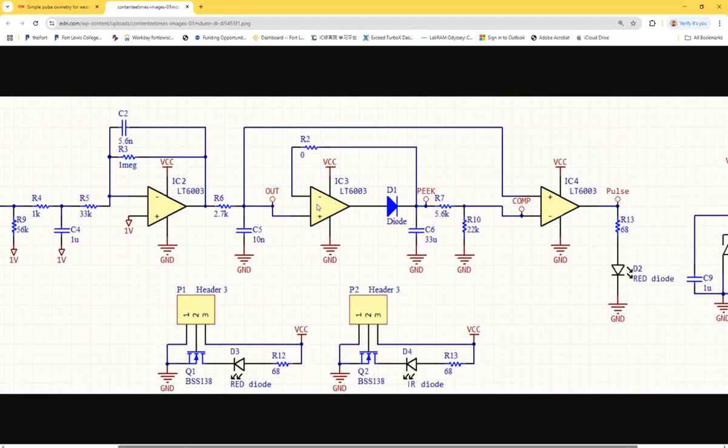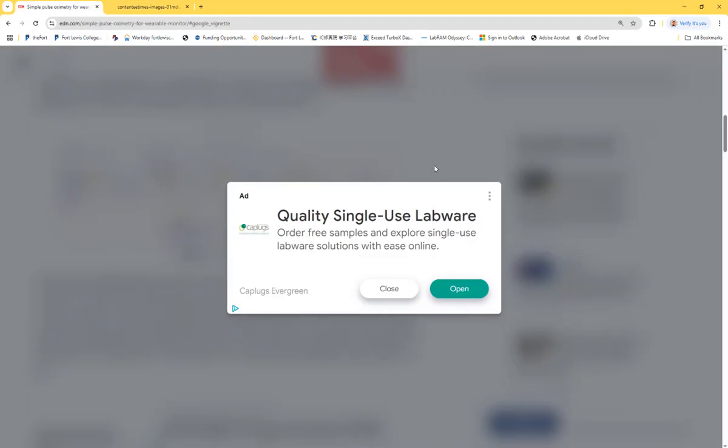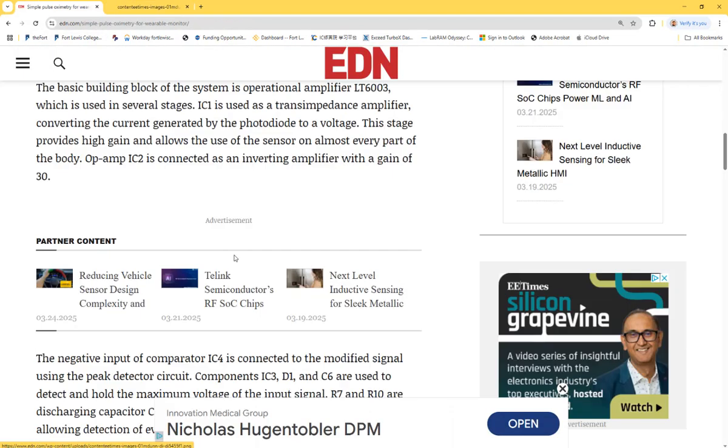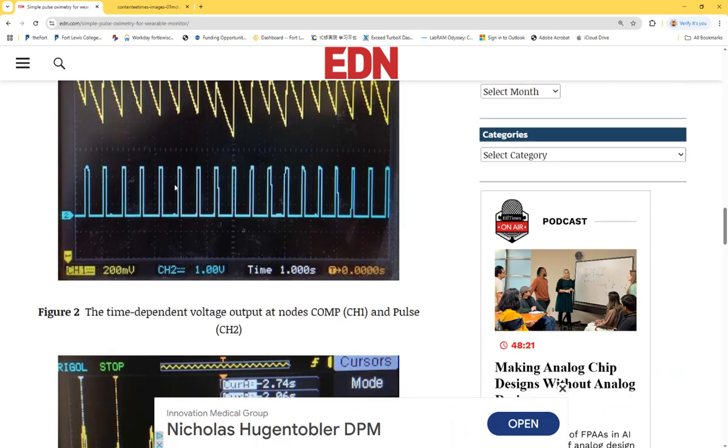And it decided to make a voltage follower. You can see the voltage follower, 0 ohms. It's basically a wire. This is the voltage follower, and I think this is a comparator because there's no negative feedback. And eventually, I think this stage and this stage help the circuit to form the DC spikes, which is not necessary, but they decided to do it.